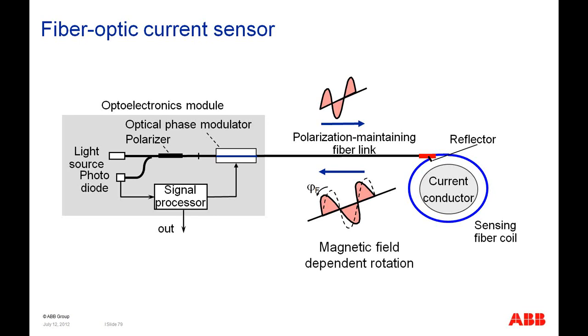It's a very simple concept, and when we first put these in for our first applications, the output of this, of course, is a very, very low level, and we actually put amplifiers on this to feed it into a microprocessor relay that was a 5-amp microprocessor relay, so it had to take a lot of current through our amplifier. After a while, it was determined that wasn't a very good approach to take. But now with the modern microprocessor relays, we can feed this low level into the microprocessor directly, and it's an analog value, or you can process it and have a numerical sample value that will go into the relay instead.